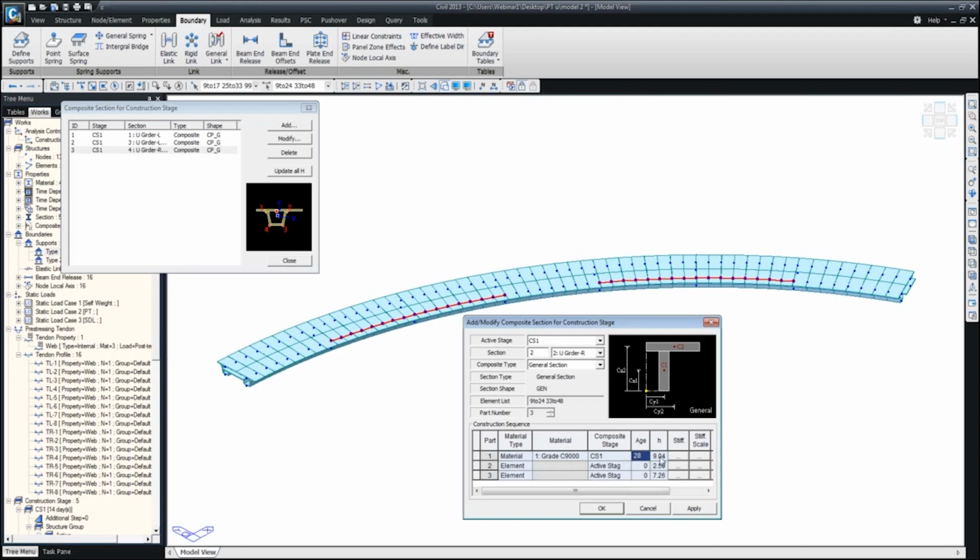By the way, for those who don't know what notional size is, you probably know it by another name, volume to surface area ratio, or something similar. It is a different formula, and this terminology is taken from the CEB-FIP code. If you need more details, feel free to ask me in the question box, and we'll talk about that in more detail at a later point.